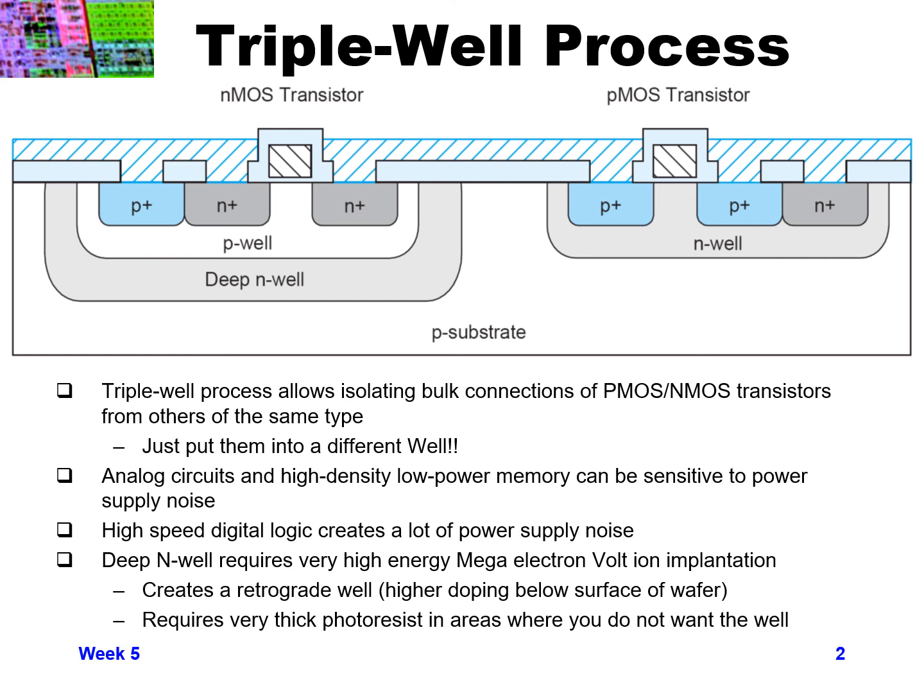So basically, the reason why you might not want to do a triple well process, you can see that it's an additional step to create the deep N well, and it's also an additional step to create the P well. So it's more costly, and it could potentially have effects on your yield versus just using NMOS devices in the P substrate because of the additional steps.